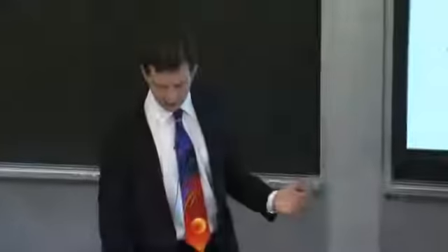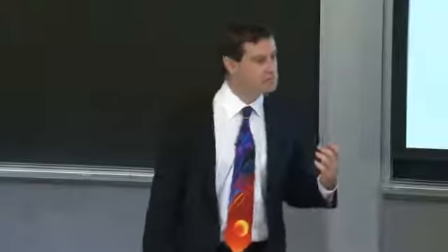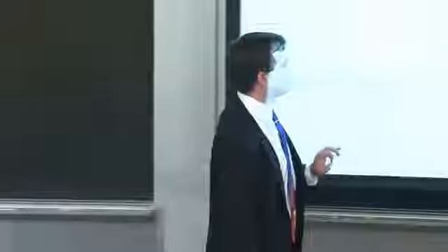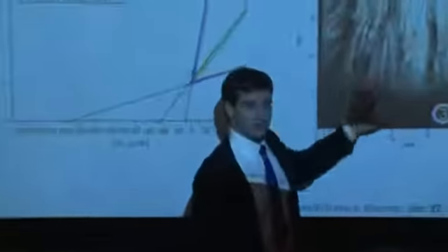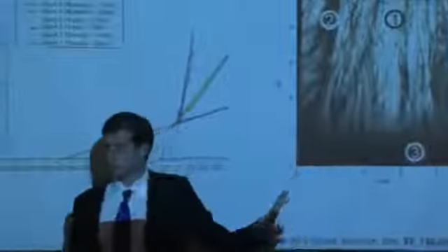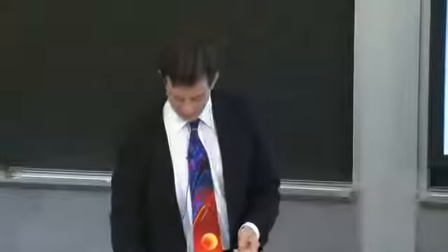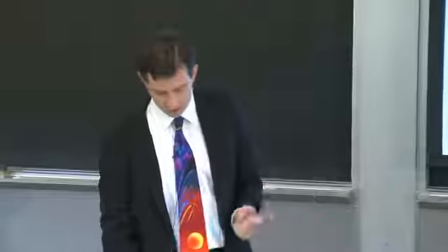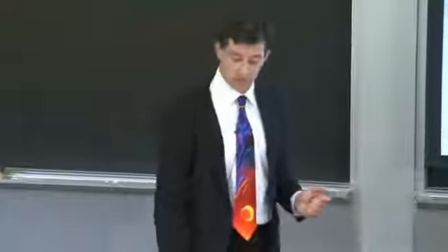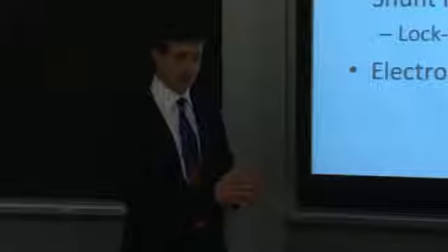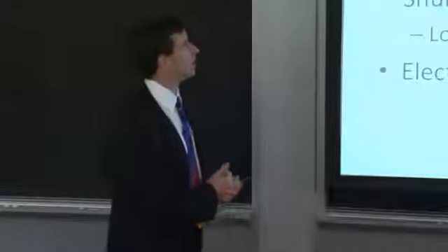So you're not testing your solar cell under ideal operating conditions. It's essentially an artificial operating condition simply to probe bulk property characteristics, right, to minimize the effect of the junction. Now, if you really want to see how the junction is behaving, how that charge separation is going, you might want to venture into forward bias conditions and eventually into open circuit voltage conditions to really test what the junction quality is instead of just probing bulk properties.